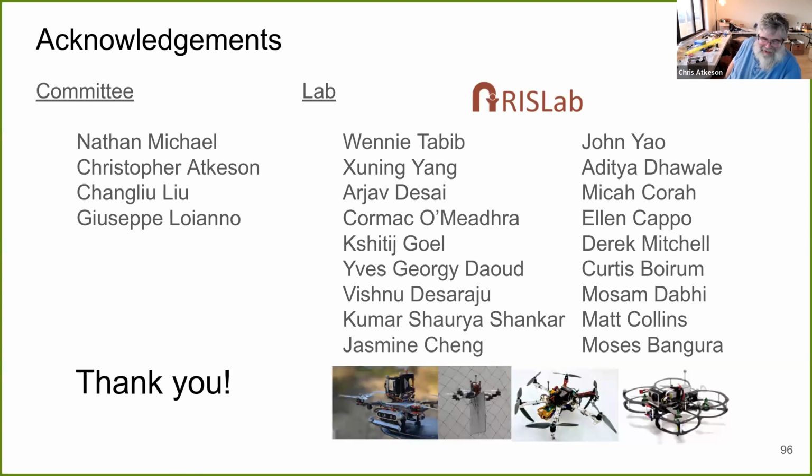So my final question is, is all of this totally esoteric, limited to quadrotor stuff? How are you going to apply it? Should anyone else care? Yeah, I think there are two points that I want to make. The first is that people should look at the dynamics of their models, like the learned models. A lot of people learn acceleration models and they don't look at the derivatives. I think that can be useful in a model predictive control setting or even some inverse dynamics setting like I do here, where you can locally predict what's going to happen using the derivatives. That's one thing. And yes, I think this model learning approach can be used in other systems, of course.